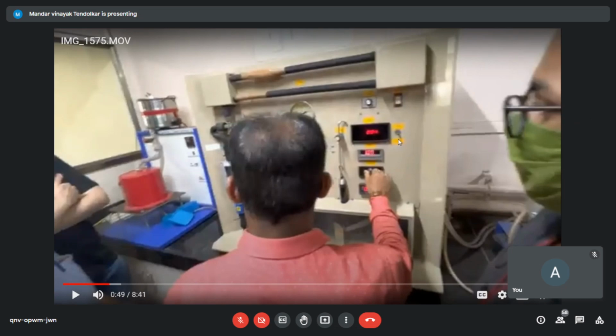Here there are two knobs. If you put it on the downward side, it will be the evaporator wattage. If you put it on the upper side, it will be the motor wattage, means basically compressor part. So compressor wattage, you need power to run the compressor also. So you shift the knob on the upper side, it will give you compressor power. If you put it on the downward side, it will give you the evaporator wattage, DC power. Fine. It's just a multi-shift knob. Fine. Any doubt? Yes, sir. Okay.